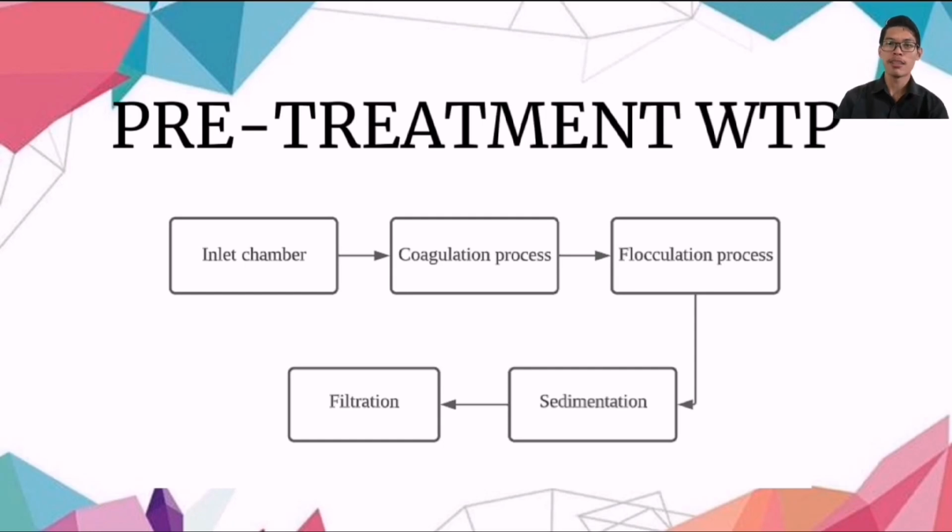First of all, the water passes through the inlet chamber, where the water treatment uses one or more chemical disinfectants such as chlorine, fluoride and lime to kill any remaining parasites, bacteria or viruses. Before the flocculation process, the water goes through a process where it removes suspended solids and natural organic matter such as gravel, sand, algae, clay, iron, protozoa and even bacteria. Many of these contaminants can give water an unpleasant taste and orange color when present in large quantities.